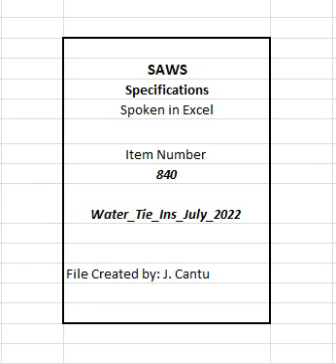8. No additional compensation will be provided for tie-ins, and any related costs, accomplished outside of normal working hours. 9. Prior to installation of tie-ins, all materials and equipment to complete tie-in work shall be on site and verified by the inspector prior to beginning any associated work. 10. If system allows, multiple tie-ins must be coordinated and approved in advance with SAWS inspector, but multiple tie-ins may not be guaranteed.